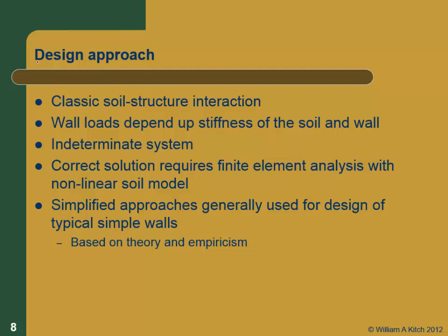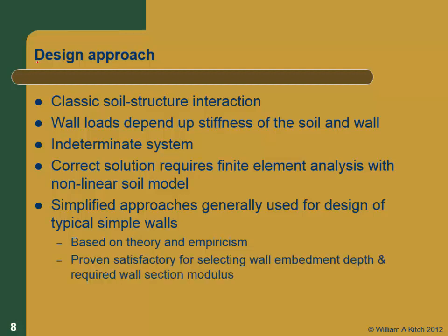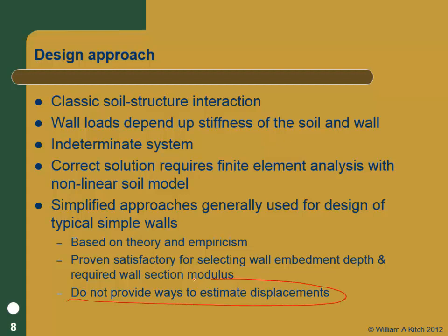These are both based on theory and empiricism. They're very common design techniques that are used and have proven through time to be satisfactory. And we're going to be using those today. But the one thing they don't allow you to do is to estimate displacement of the wall, because they explicitly don't include the stress-strain relationship of the soil. So if you need to estimate displacements, then you do need to go back and run a finite element solution with a nonlinear soil model.